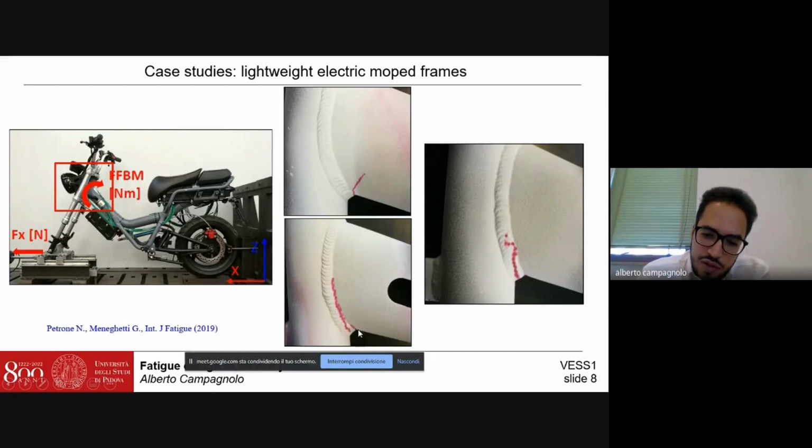In this figure, instead, we can see that the cracks initiated again at the welded side. After that, it propagates along the weld toe profile. In this other figure, instead, we can see that no crack initiated at the welded side. However, the crack seems to initiate in the middle of the weldment. This is the typical cracking behavior when the crack originates from the weld root side, which is hidden in this figure, so that we cannot see the location of the crack initiation. We can see it only when the crack emerges on the weldment surface.